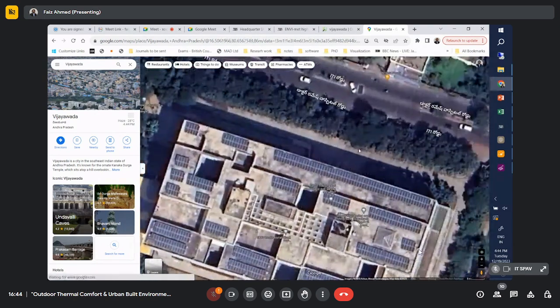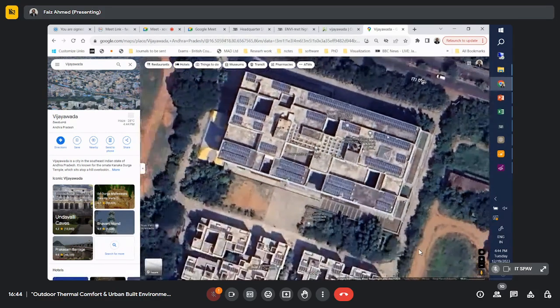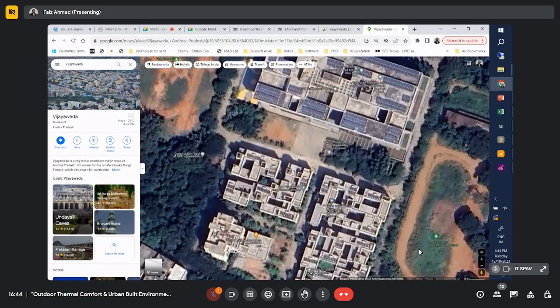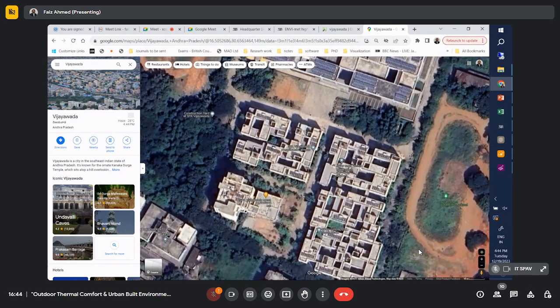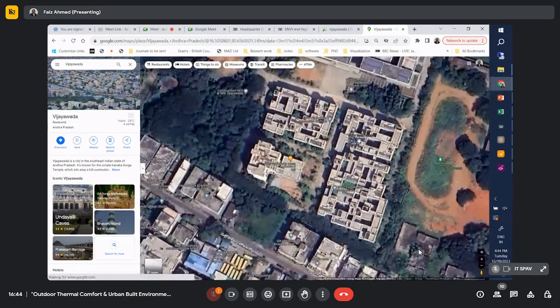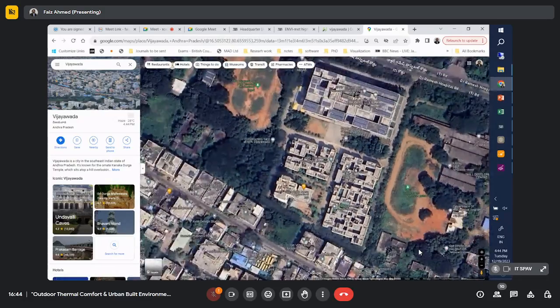You can just go around, check the height and size of the vegetation, and then assign that. Of course, building height is 25 meters. If you keep two grid size, you will be able to accommodate 12.5 meters. You should be fine, within the free grid size that we have. So if you can simulate for this, it will be great.